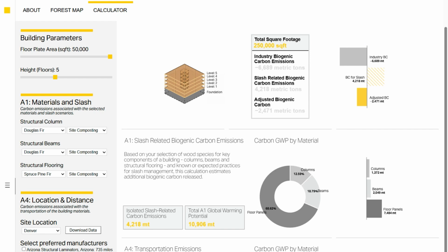Reiterate what part that is. Yeah. So the industry biogenic carbon is the value that you would get from a typical EPD, right? And that is by defining where the boundaries are between A1 through A4 life cycle stages. So, for example, what you get out of an EPD will typically not include the forest level biogenic carbon. That carbon life cycle is typically excluded from the EPDs, and that's designed as per ISO standards. So it's this industry standard.